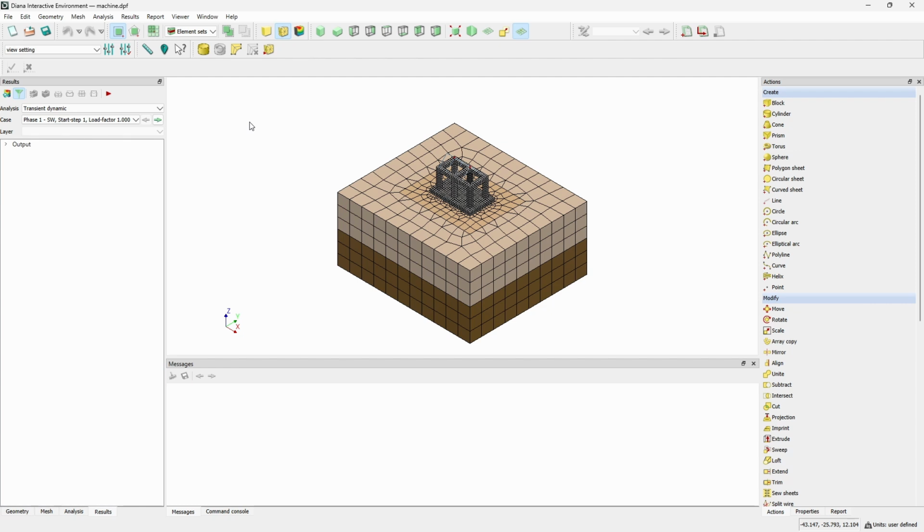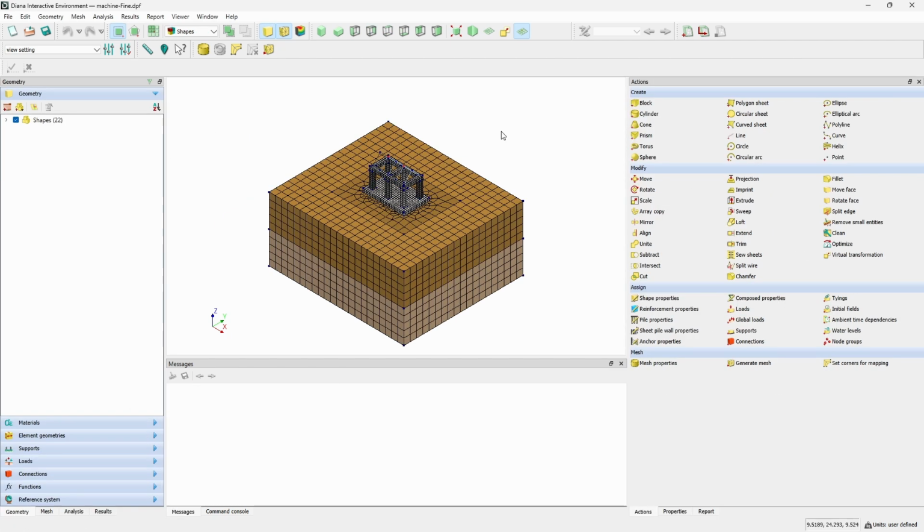In the final step, I want to check the displacement in the perfectly matched layer to ensure that they are effectively absorbing vibration. Since this tutorial is using a coarse mesh, it's recommended to have at least 5 elements across the PML region for better accuracy. Based on this recommendation, I have changed the meshing of the PML region to a 2-meter element size. And let me show you the second model that I have changed the meshing for the PML region.